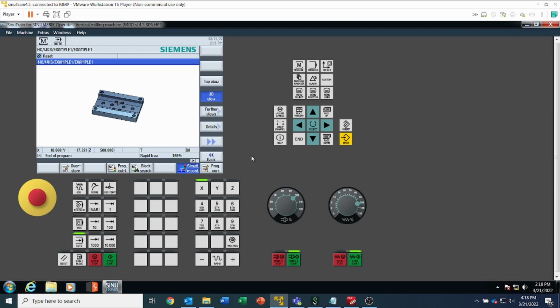The idea here is you obviously don't want to watch your entire process being machined if this is an 8-hour part, but you can play around with the time sequence if you want a 1-to-1 ratio, or if you're just running through a programming scenario to check for collision avoidance or any alarms that might occur before you bring it down to the shop floor. Because when your machine is not running, it's not producing parts, it's not making money. Having the ability to do this in a virtual environment prior to going down to the shop floor can save you tons of time, effort, and troubleshooting if anything was to go wrong out there.